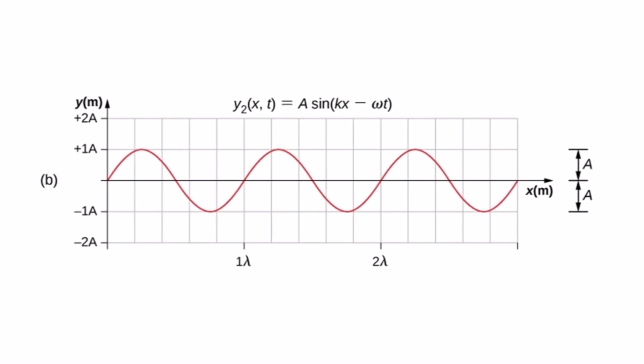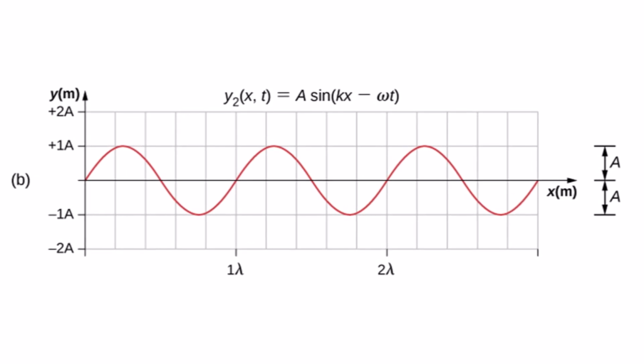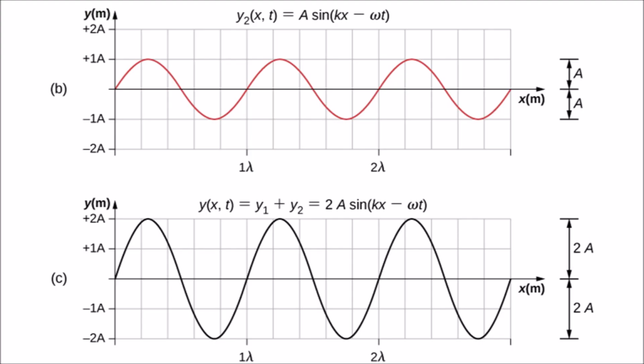So let's, for example, take a 440 hertz sine wave. Just keep it simple. An A standard sine wave with a constant amplitude, we'll just say it's 1 volt. Well, if we take this ideal voltage source and apply a gain factor of 2, that is to say we have amplified the signal, ideally, meaning we don't introduce any other artifacts or things that we don't want yet, then we'll now have a signal with an amplitude of 2 volts because we have doubled the amplitude. That is how ultimately you calculate gain.